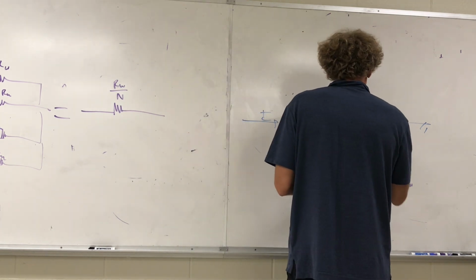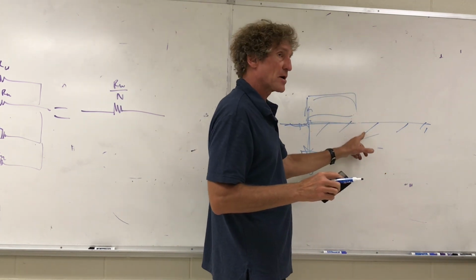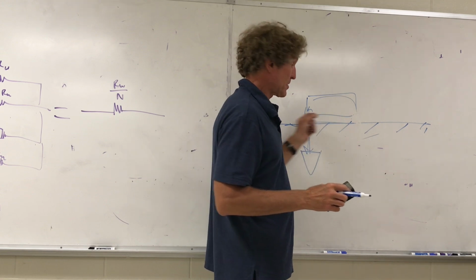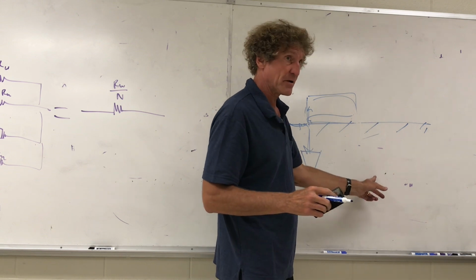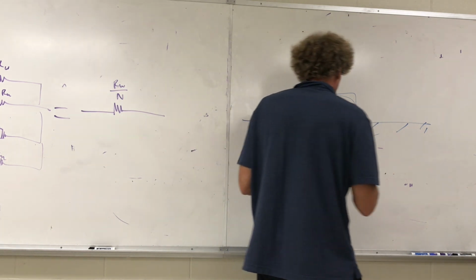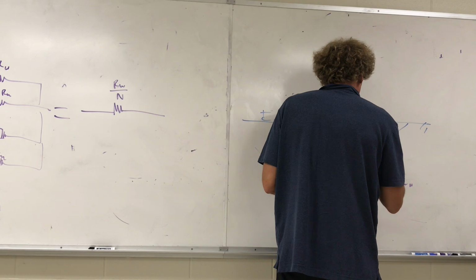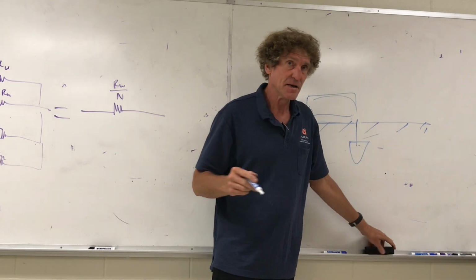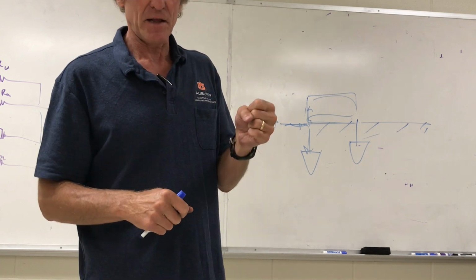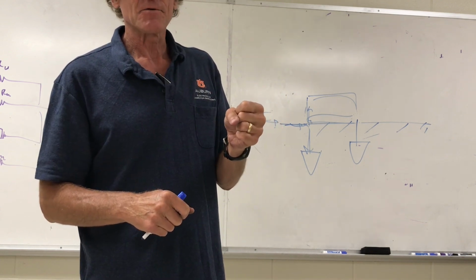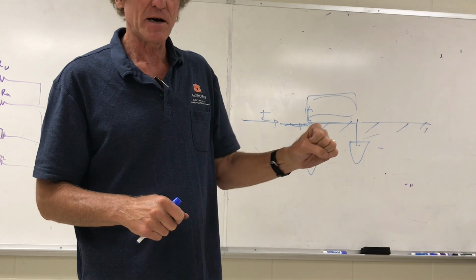So they may have something where there could be an arc to the ground if the current caused a significant amount of voltage, where it would flow through there and possibly cause a fire. Or somebody could have accidentally put in two effective grounds. Maybe somebody had a metal pipe or something to secure something. There's a lot of ways to do this. Water lines are the worst. These metal water lines, you can get it.